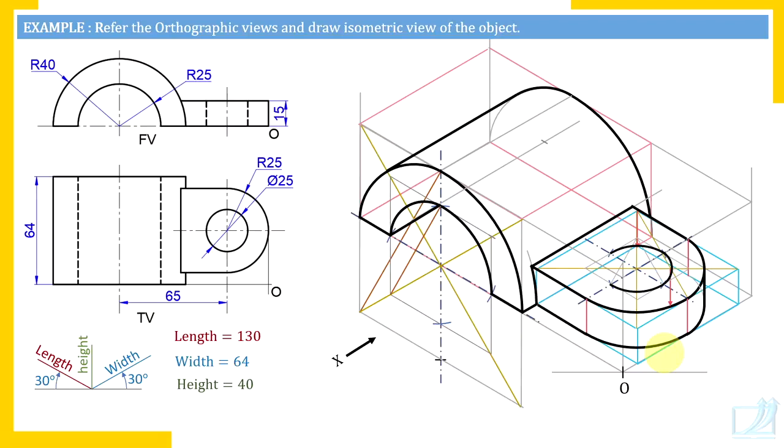And if you have any doubt about drawing this isocircle, then go through that video. It's about a 15 minute video. Go through that video in which I explained the manual drawing procedure of the isocircle. So this is how we have completed the opening of the isocircle. And now there is the opening of the hole on the top surface and a similar opening on the bottom side. Since it is a thin plate as compared to other dimensions, there is a possibility, I am saying possibility, that through this opening on the top surface, some portion of the lower opening is visible.